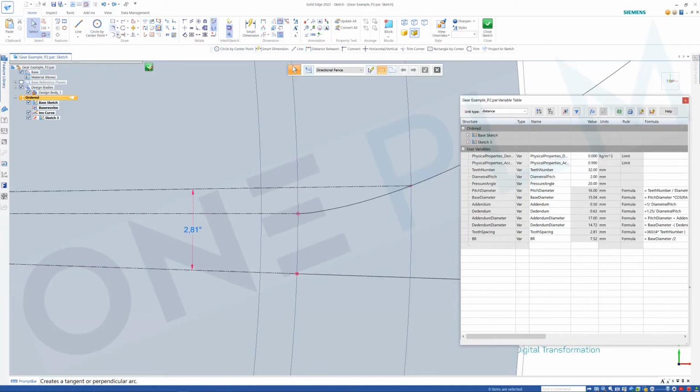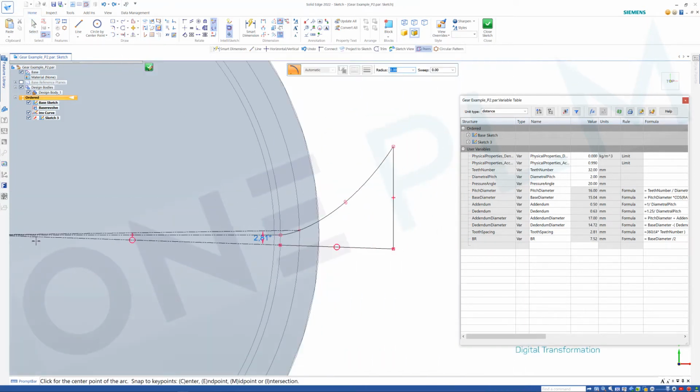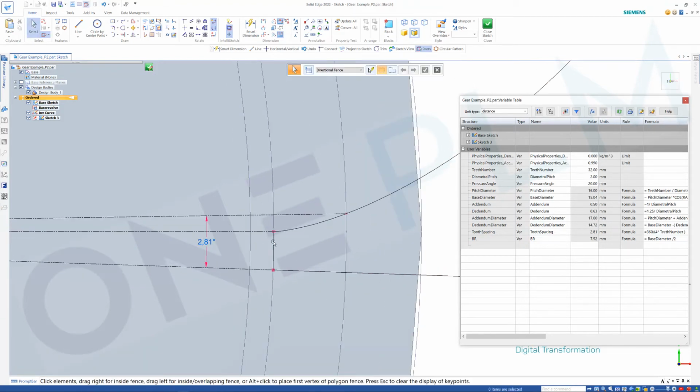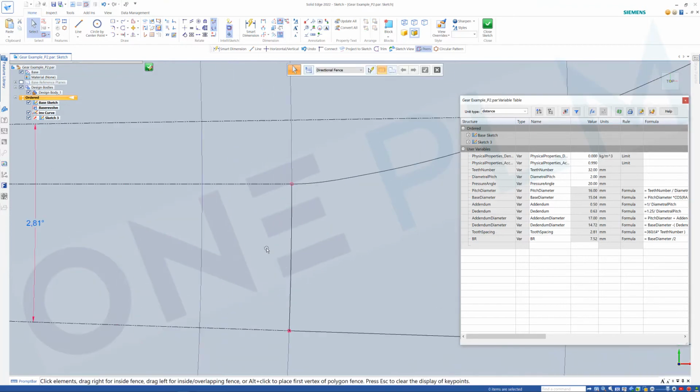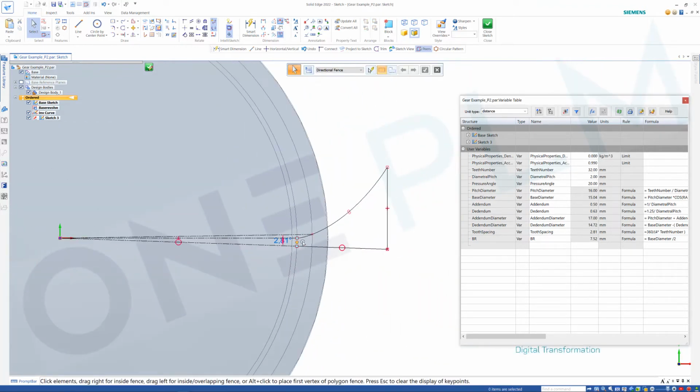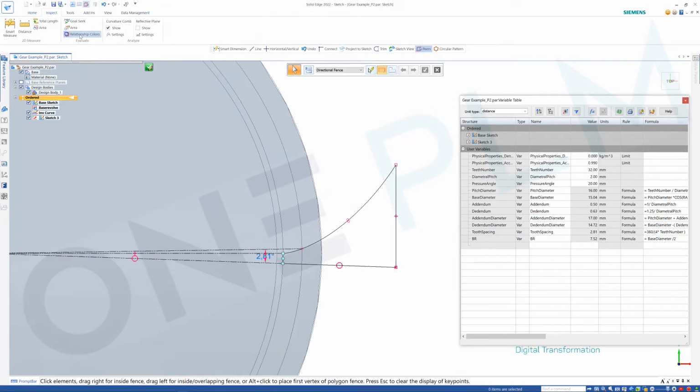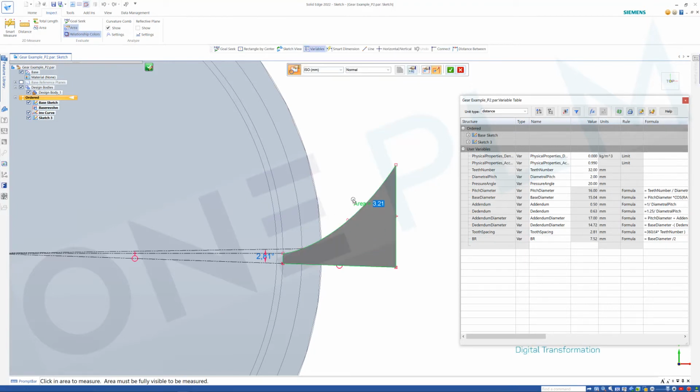Solid Edge can do this weird thing where it starts to create it the wrong way. So in that instance, when we do our arc by center, it might be easier to start it from the bottom one. That will then start to go up, and then we can hover over that one and use our E key to go to the end on there. And that's going to create that line. So we've now got our region on there. We can check we've got our region by doing an area check, because the area tool is going to create that area for us.